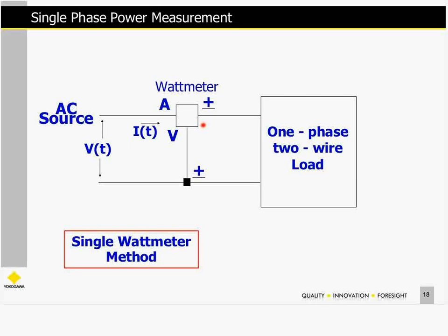And we're going to measure the current in series in the line, and we're going to look at the voltage from line to line. And you'll see I do put polarities on there. These are instantaneous polarities. The wattmeter, the power analyzer, on the input terminals will have these polarities. So it's important that we follow the polarities mainly for phase. So we're looking at 2 variables of voltage and current, and we do have to have the right phase relation to make the proper calculation.